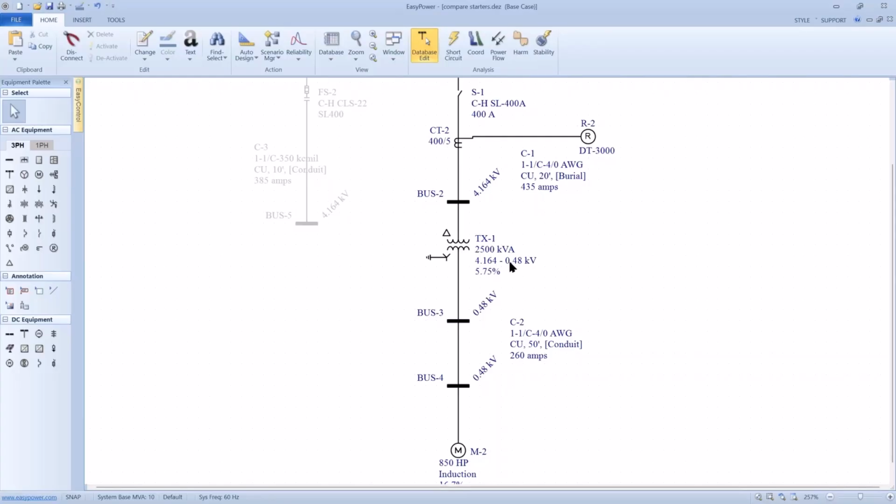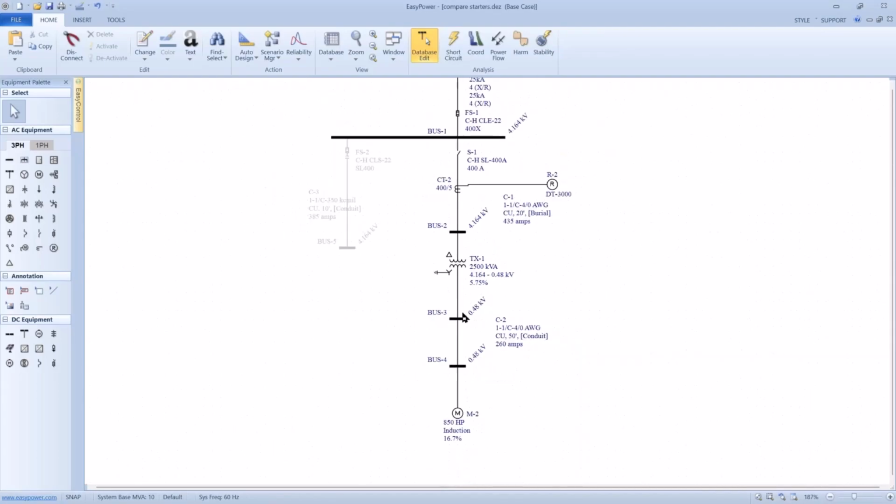And I have a considerable step down in voltage. So I'm curious why I picked the size of this cable as it is. It just could be a downright mistake on my part. Okay, so there's two things I want to get to. One is I need to deal with this ampacity, and second, I want to make sure that we have coverage by this current limiting fuse.